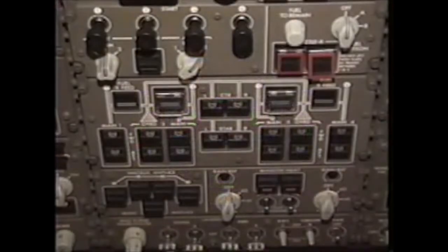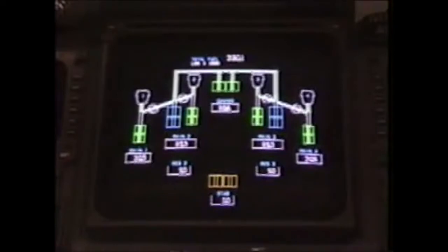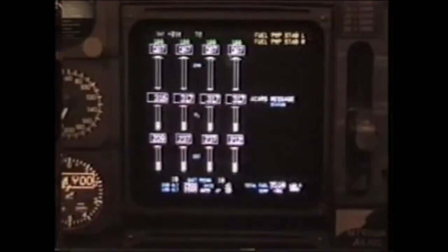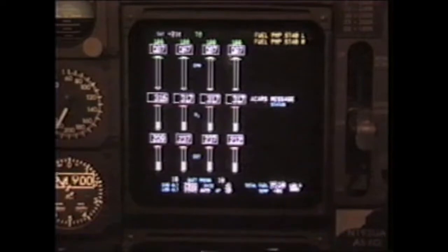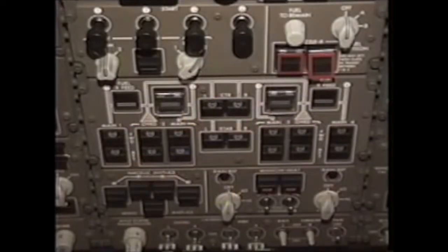The next fuel system change occurs with an ICAS message of stab pump left and/or right. This would require the crew to bring up the fuel synoptic and verify that the stab is in fact approaching empty. With regards to stabilizer fuel, no crew action is required until both stab pump left and stab pump right messages are indicated. With both messages indicated, the synoptic for fuel will be verified that the tank is in fact empty. Whenever the flight crew changes fuel panel configuration, the other crew member should always be advised.